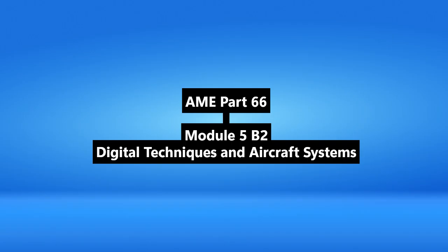Then at the other end, you need a demultiplexer, demuxing. It takes that single input line and distributes it to one of several possible output lines, again based on select lines. Sending the shared signal to the right place. Precisely. And as we mentioned, a decoder like the 74138 can often be used to control the select lines of a demultiplexer. Time division multiplexing, TDM, is a common technique where different signals get assigned different time slots on the shared line. Everyone gets their turn on the channel.